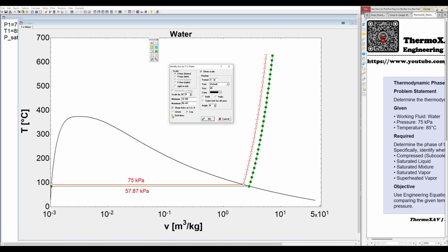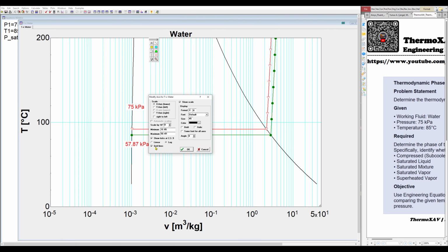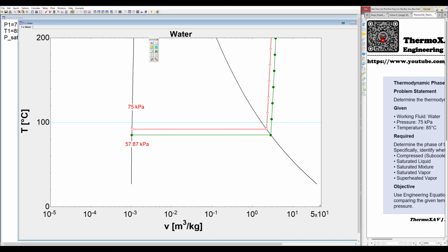And then I can also activate this grid line for the x-axis. Then for the y-axis, I will go here and change this 700 to like 200. Activate the grid line and then press on OK. Here you can activate the minor grid line as well. So for now I can activate like this, but it seems these vertical lines are not necessary. I will go back again to the modify axis, disable this one, just keep this one.